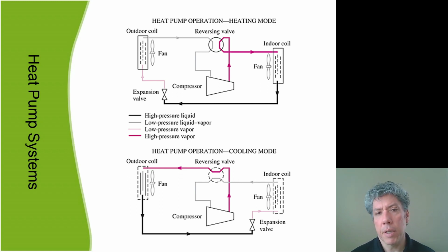So anyway, typically you want the refrigerant to go down to 45, 50 degrees, something like that, maybe 40 degrees, but you want it to be controlled so that as air moves across the indoor coil, it's cooled, and then the refrigerant that has gained energy goes back to the compressor. Now you wouldn't want liquid refrigerant going back to the compressor. So in this case, the indoor coil would be known as the evaporator, because what's going on is the rest of the liquid refrigerant is being boiled off by the air. Heat is flowing from the air that's in the home to the cold refrigerant, boiling off that refrigerant. Now notice that the refrigerant temperature remains constant, which is an interesting thing.